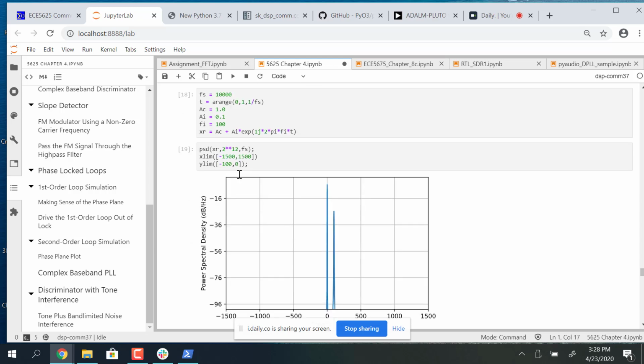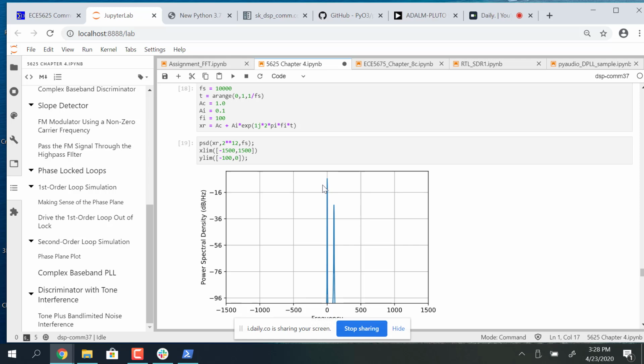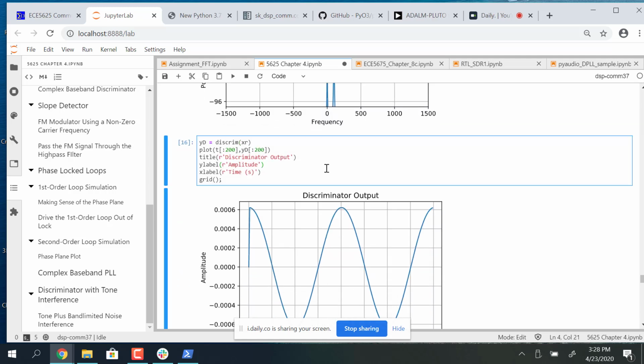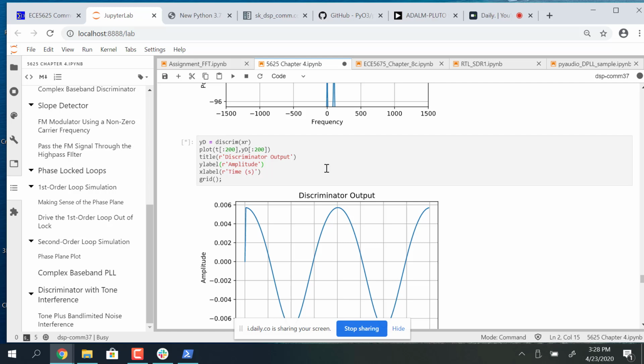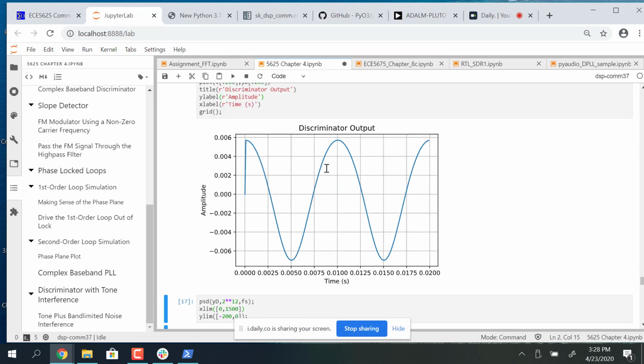And in the spectrum, you'll just see that this interfering tone has risen up closer. But now we're starting to see some asymmetry like we saw in the mathematical plots I have in the notes. I don't know if your eyeball is picking it up, but the top of the cosine wave is kind of fat. The bottom is kind of getting narrower.